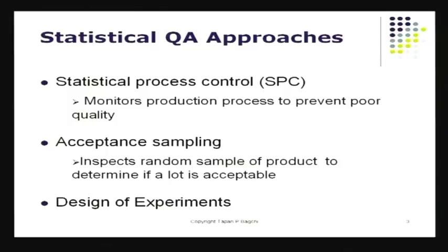In the old days, the only way to control quality was by inspection, and the statistical procedure which we covered in the earlier sessions, one of those was called acceptance sampling. You basically collect a few samples from a handful of items, and based on the quality of these samples, you decide whether to accept the lot or to reject the lot. That particular procedure was called acceptance sampling. That was one way to apply statistical methods in quality assurance. And this online control business comes under statistical process control or SPC. This is like the second class of applications of statistical methods in monitoring quality, in assuring quality.